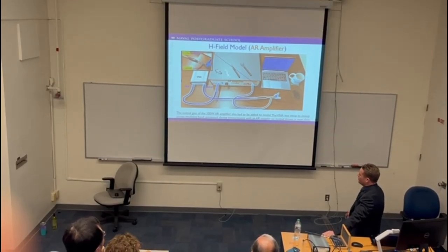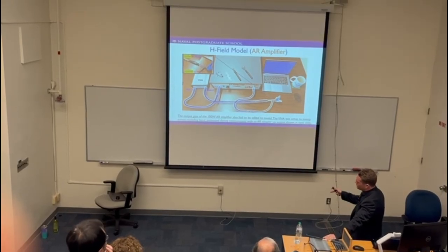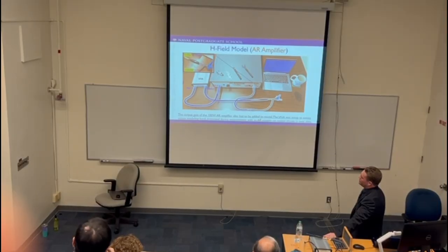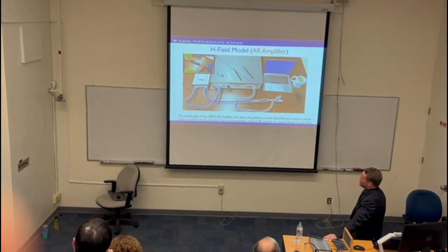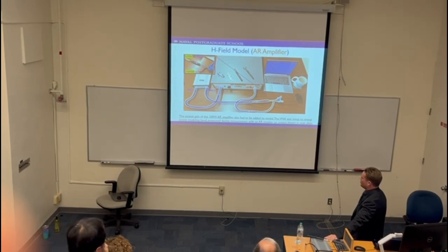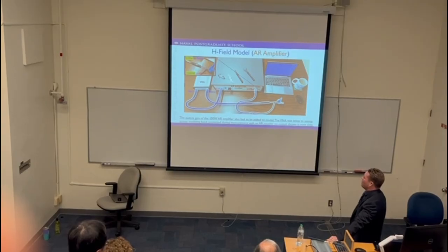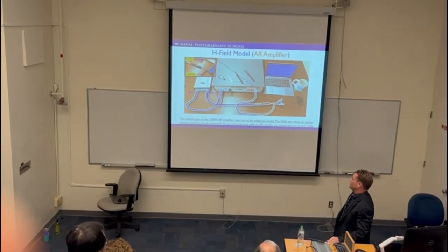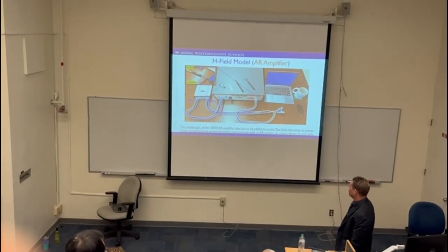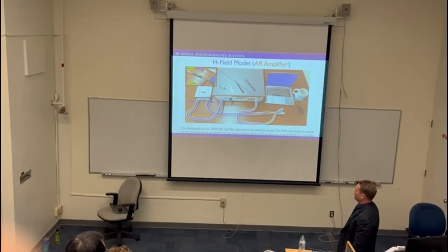In order to do that, you can see here I plugged in port 1, so basically injecting a signal. In a VNA, just real quick, you can think of port 1 as a signal generator and port 2 as a spectrum analyzer. I am injecting a signal from port 1 into the input of the AR, and the AR amplifies that. The output of the AR is then looked at from the spectrum analyzer side, port 2 of my VNA, and I'm able to use all that data to begin to model how the AR is behaving across our band.